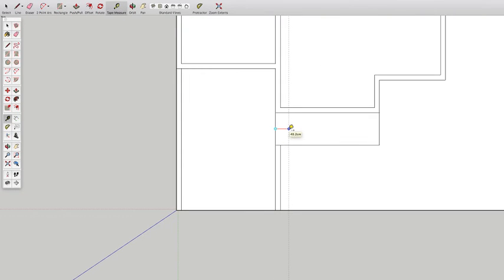Get back to my tape tool, and then I'm going to go 7.5 this way. Why did I go 7.5 this way? Just because I want to make this one in the middle, because I want to put a window in this wall. All the wall is 15 centimeter, so I'm going to take 7.5 this way and 7.5 this way. That makes the midpoint of the 15 centimeter.